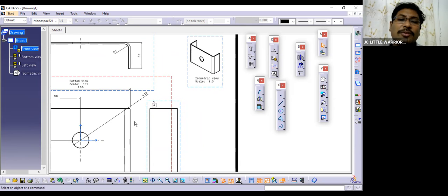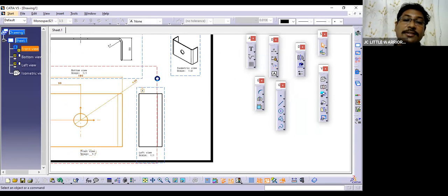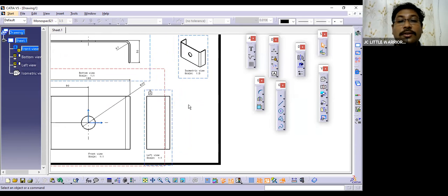That is the easiest and genuine way. If they ask for some dimensions and it is very difficult for us to get those dimensions, in that case, with prior intimation to the OEM, we are going to modify it. Because in 3D there are some problems and we couldn't get it, that's the reason we are modifying this. Then if they say yes, go ahead, only then is it okay to modify the 2D. Otherwise, it is always good to project from the 3D.